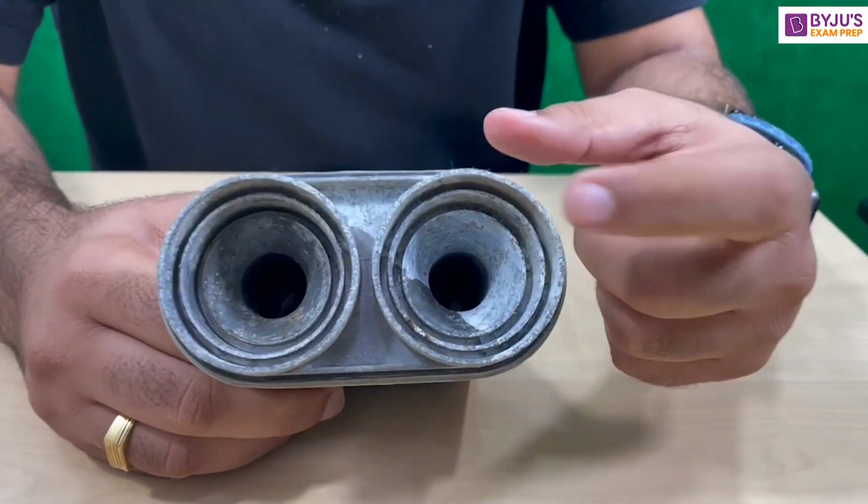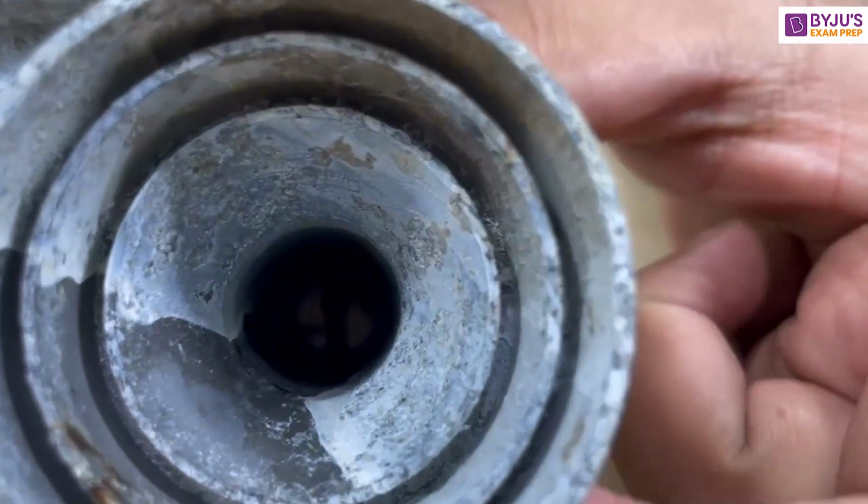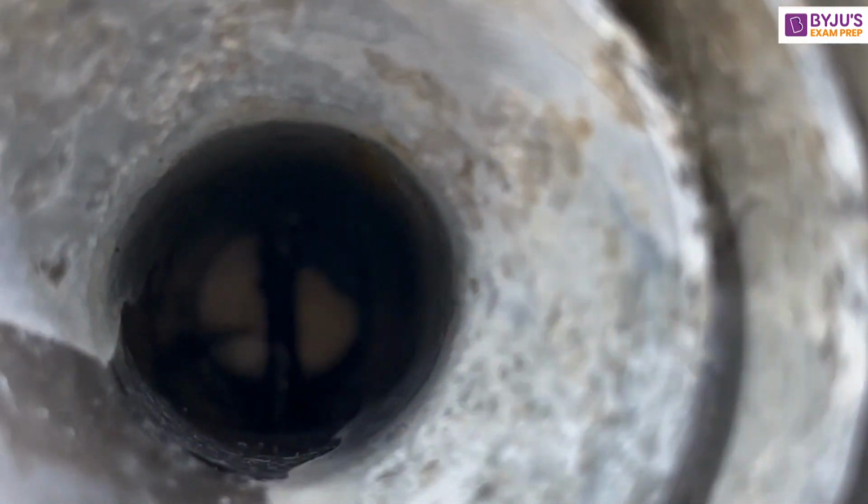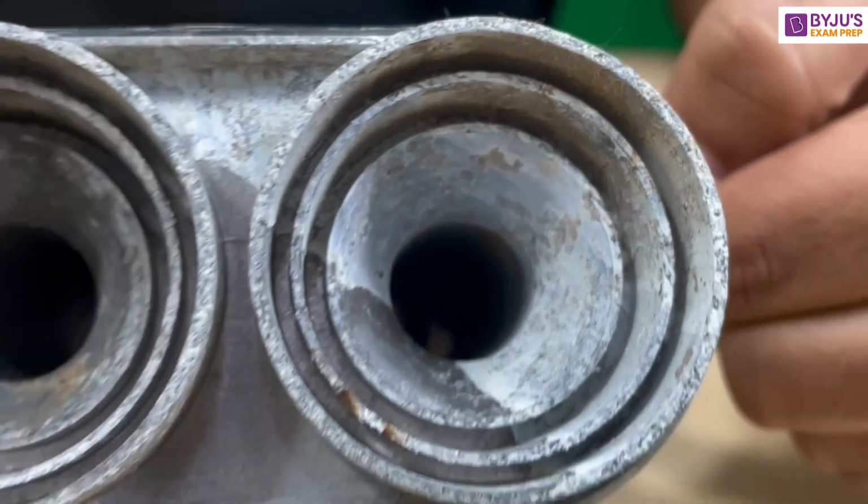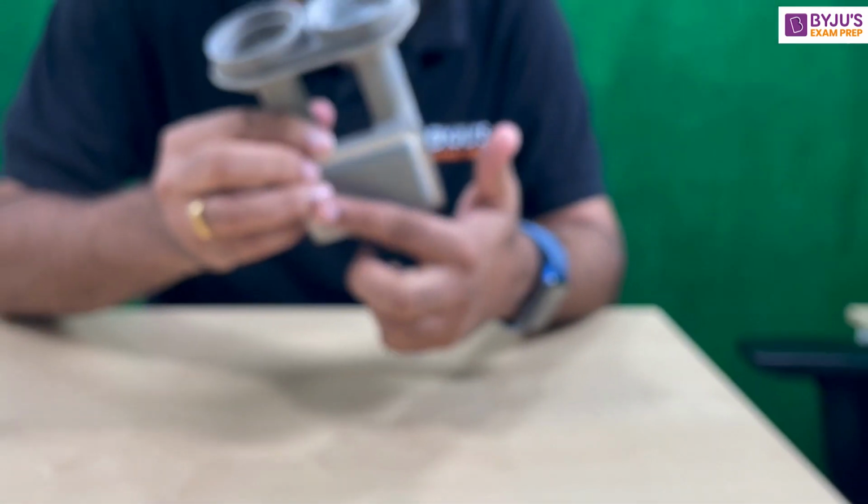So from one of the antennas which was not operational, I have got this LNBF also to show you the internals of it. So this is the low noise block down converter with the feed horn. Let's come closer to it and watch into it. So at the front you are able to see the horn antenna connected to the waveguide, finally to the probe. As you are able to see, inside, the probe is connected, right? The probe then transfers or sends the signal to the PCB, which is inside this particular module.